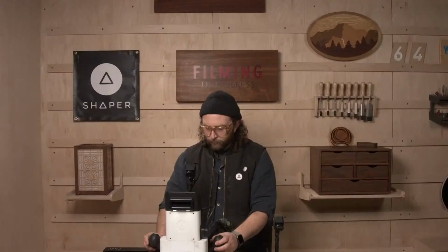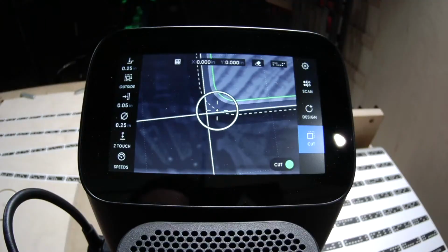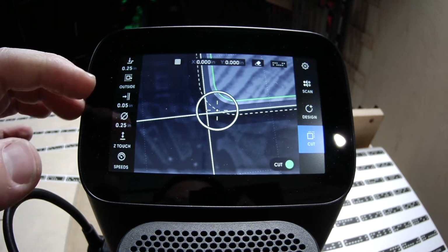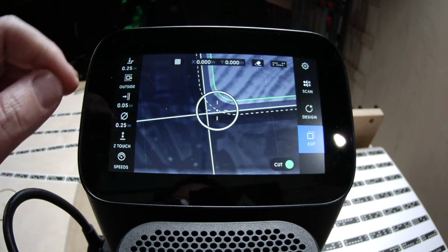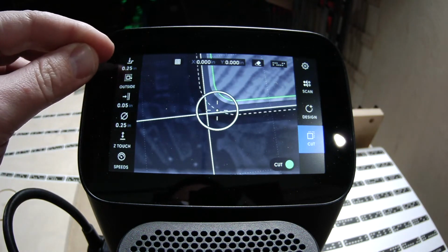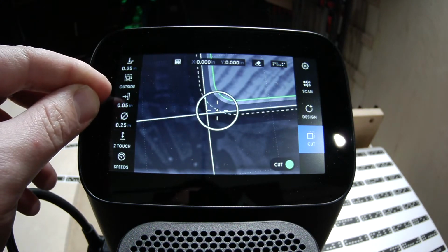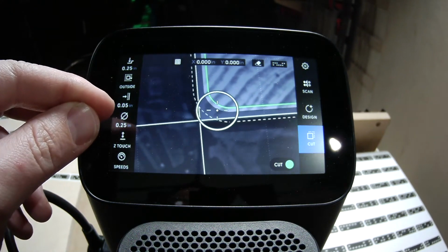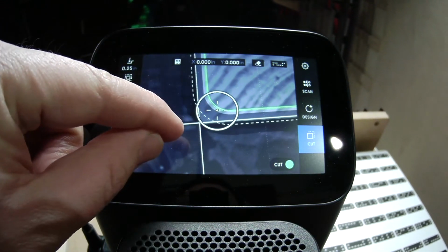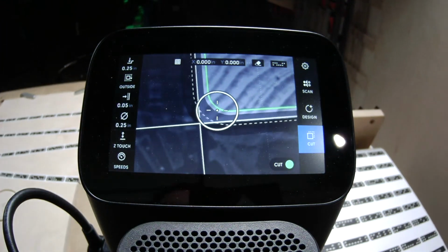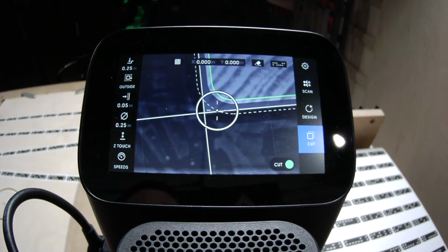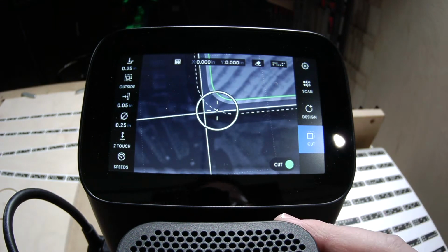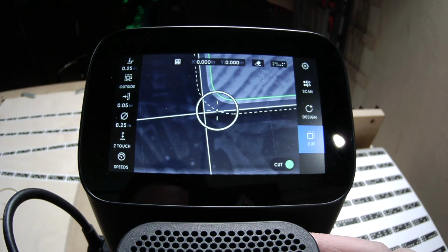But we're doing 1/4 inch increments down to 3/4, and we're going to do a rough pass first. So we're going to have a small offset attached, which is here. And then when we get towards the end, we'll change the offset to 0 and finish it up. Yep. So right now, my cut settings are 1/4 inch depth, as Sean said, and 50 thousandths offset. You can see this little gap right here between the gray line and the green line. That's the offset. So I'm moving this away from its final size by a little bit, just to give myself some wiggle room and make the final result look cleaner and be a little bit more size accurate. So let's go ahead and get cutting.